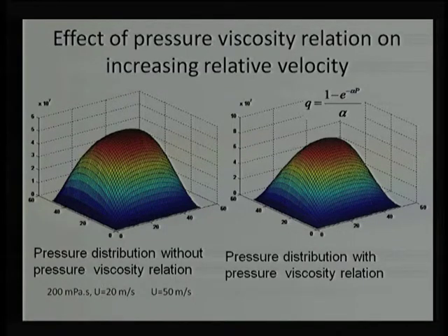We know very well under high pressure every body is subjected to deformation. If we account for the deformation, film thickness will vary, film thickness will increase. If film thickness increases, then load carrying capacity will come down or pressure will come down. So, to some extent they are self adjusting.